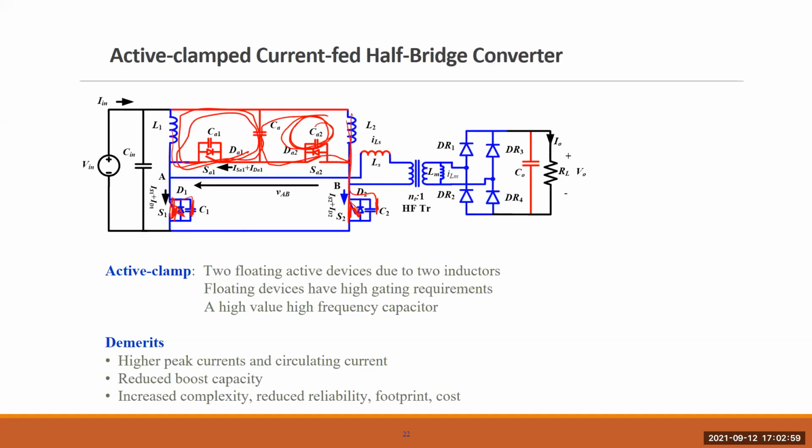Okay, so active clamping circuitry acts as a snubber to clamp the voltage to overcome this resonance for the commutation of the diodes or the switches efficiently compared to RC or RCD snubbers. Okay. So in a converter with an inductive output filter, this is quite important. Similarly, in a converter with an inductive input filter also, it is quite important.